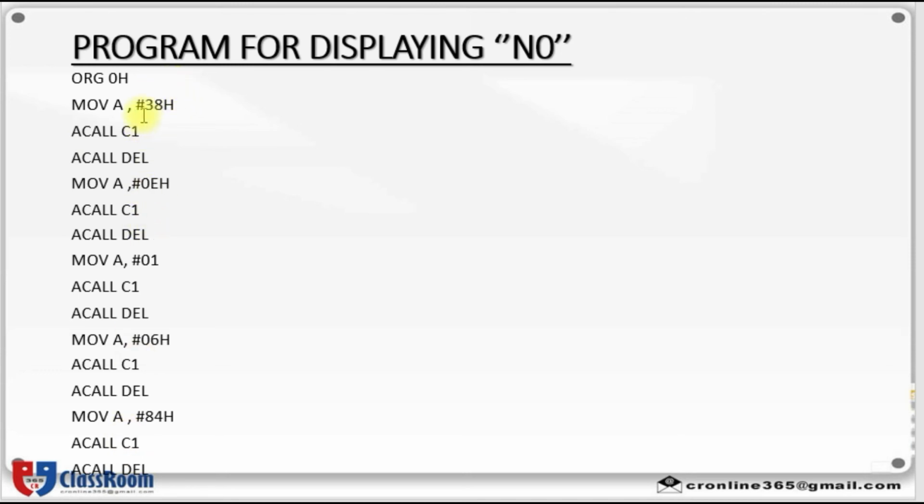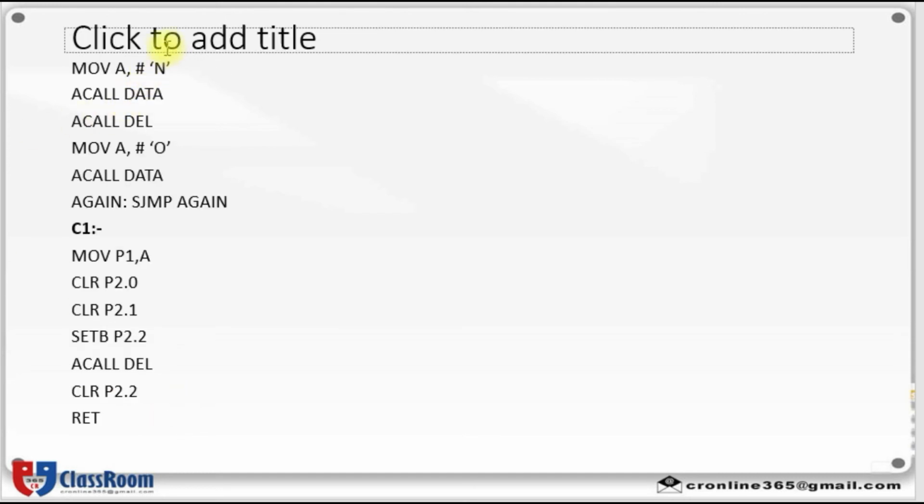So, here first 5 into 7 matrix, 2 lines, LCD is initialized. Then I have switched on my display and cursor blink. Then I have cleared my display screen. Then I have shifted my cursor to the right position. Then I have forced the cursor to the beginning of first line, fourth position. After this, I can write my data.